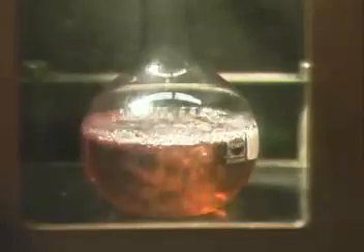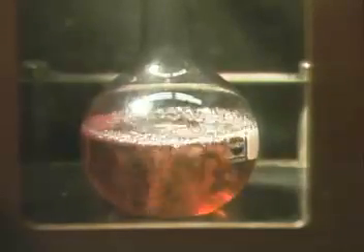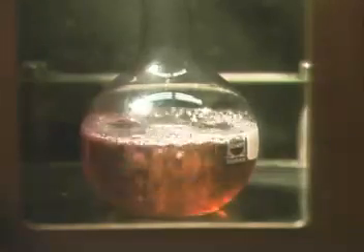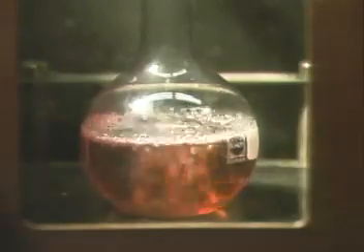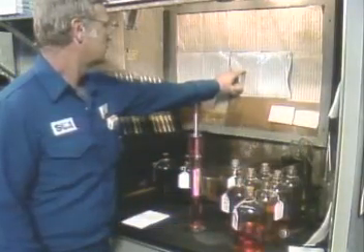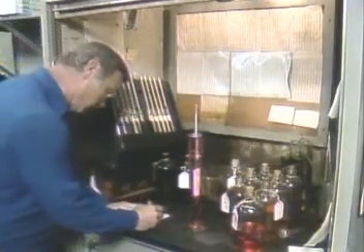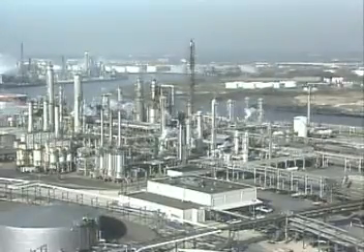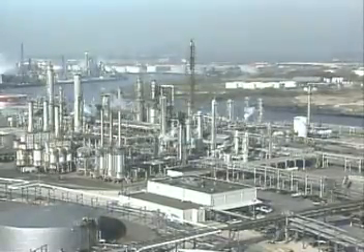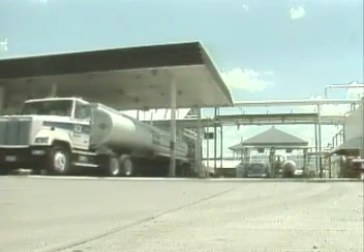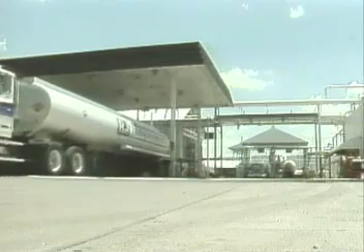When a product is tested, its composition can be indirectly measured by recording the temperatures at which the different components in the product boil. Product specs are set by the demands of downstream processes and by the marketplace. Products must meet certain quality standards. For example, a downstream process may require a feed of predetermined quality. Sales contracts and marketing practices also require distillation systems to produce products that meet certain quality standards.